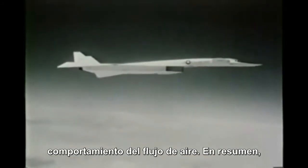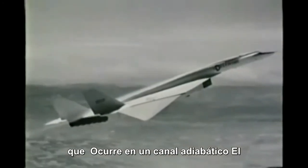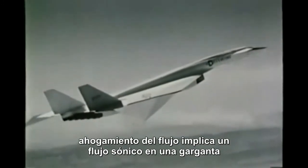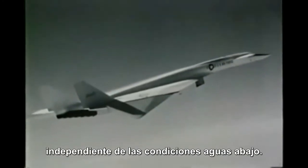In summary, we have seen 3 important phenomena which occur in adiabatic channel flow. Choking implies sonic flow at a throat with an upstream flow which is independent of downstream conditions. Blocking implies choking at 2 throats in succession with the second throat area too small. Starting implies swallowing of a shock wave and is a necessary step in the achievement of supersonic compression or diffusion in channel flow of a compressible fluid.